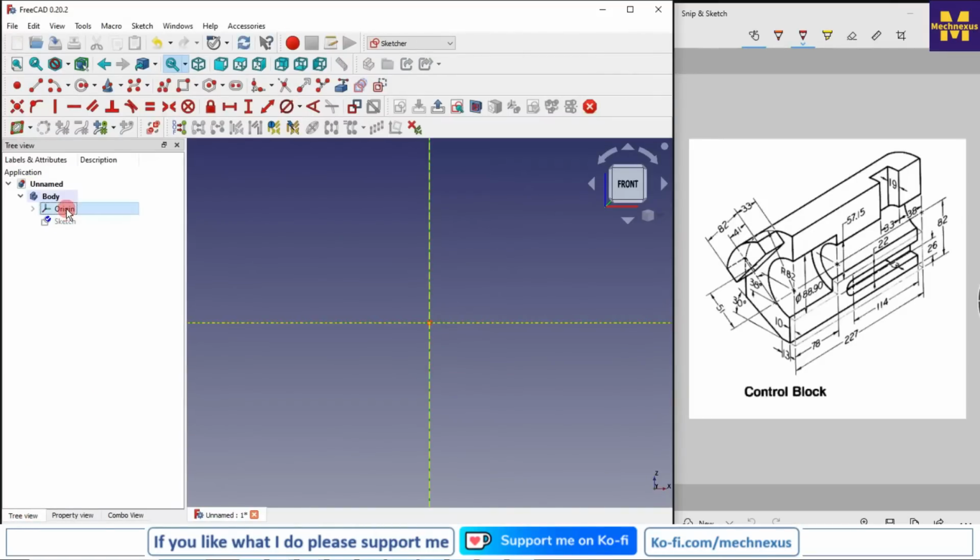Now I will go to my tree view and turn off my origin plane. I will keep this center at the origin, or I can keep this edge on this axis. So we have both the options. We have the flat face here at the bottom, so instead of this origin I will keep that flat face here because there is a material removal here. So let's start. I will select the polyline